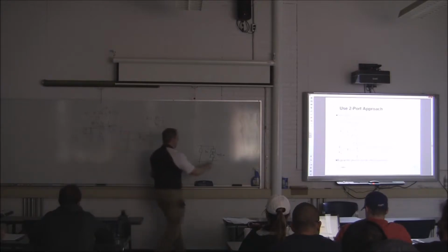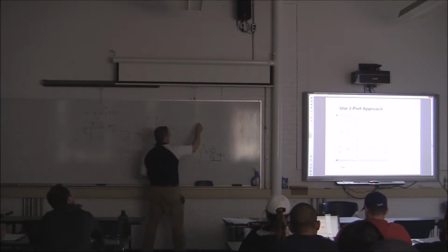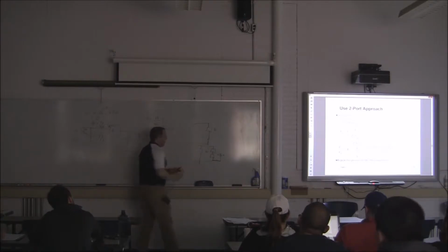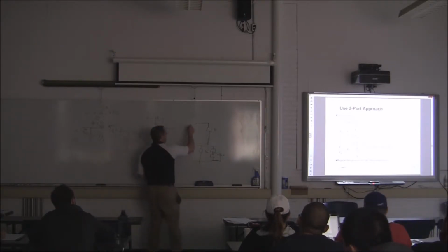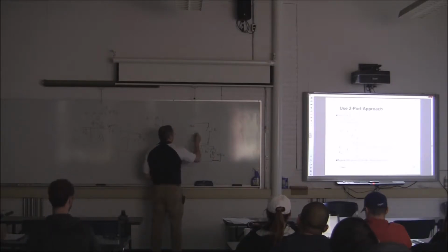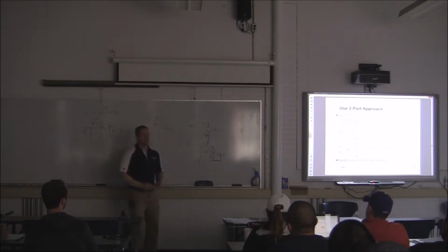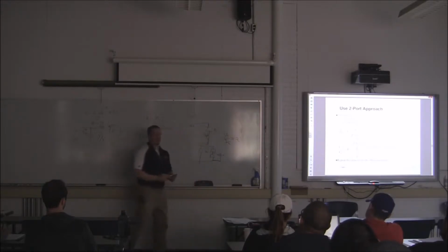Put a dead short circuit across here. So now my circuit looks like this, right? This is my Z. I've got a short circuit here that shorts out the capacitance to ground, right? This is VS. And my IR is going through here. So isn't it just Ohm's law that VS divided by IR equals Z prime?